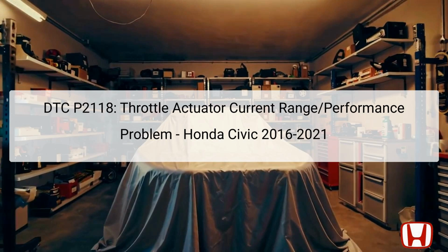The throttle actuator is responsible for controlling the amount of air entering the engine, thereby affecting engine performance, efficiency, and responsiveness. When the DTC P2118 is logged, it also means that the vehicle may experience erratic engine behavior, reduced power, or stalling since the throttle actuator does not function properly. It's crucial to undertake a systematic approach to diagnose and resolve this issue, as improper handling can lead to further complications or even additional DTCs being logged in the system.